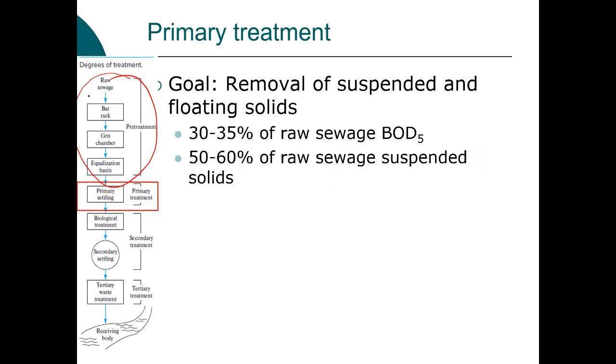Everything we've talked about so far is considered primary treatment. The goal of that primary treatment is to remove the inorganic material, protect the pumps, and equalize the strength and flow entering the rest of the plant. From there, it moves into the primary sedimentation basins.